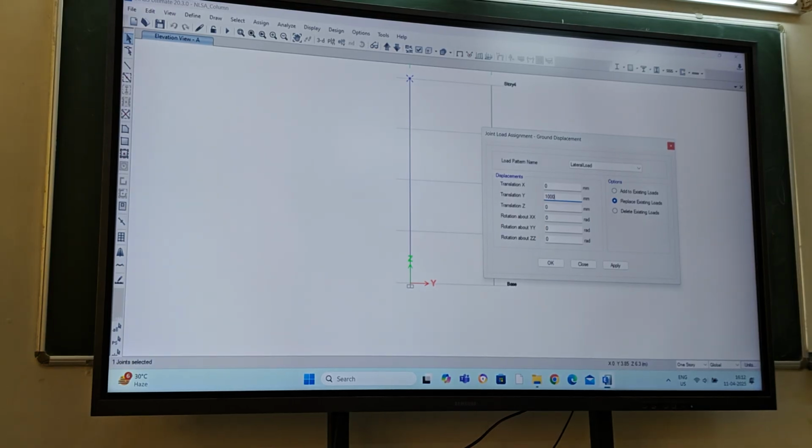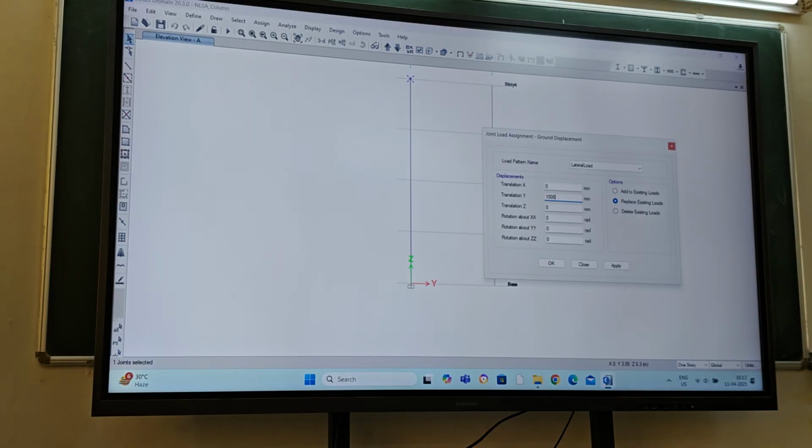So based on my understanding was when actually load is too high. Suppose your structure deflected a little bit. Now in this deflected condition, you have very high axial force. Then because of the P-delta effect, it will keep on increasing and fail. But if the axial load is less, you can sustain even under deflected condition also. So that's why I have reduced the axial load.